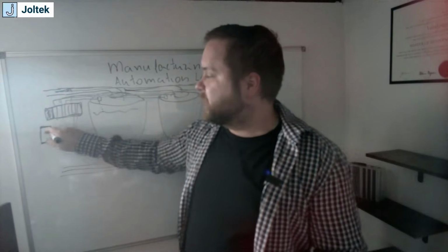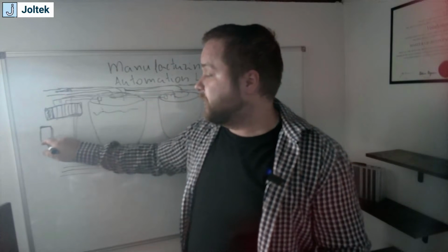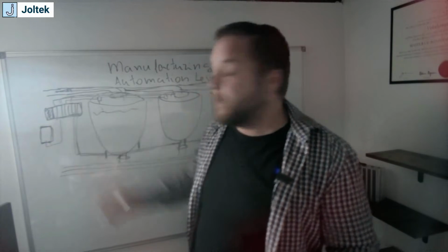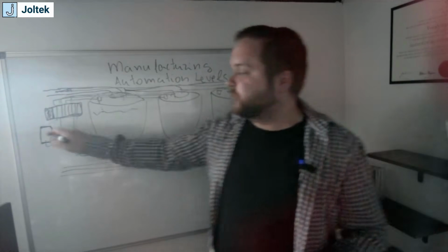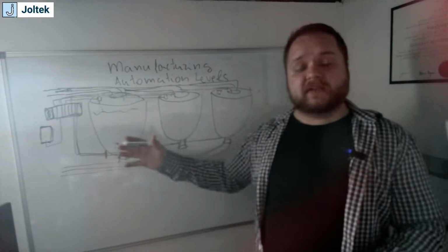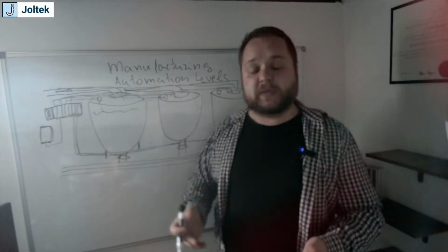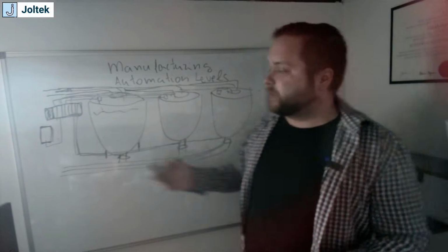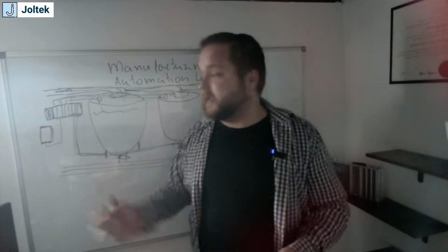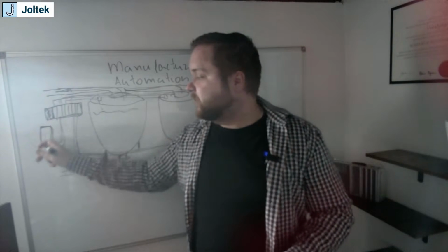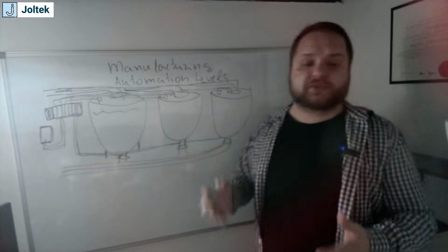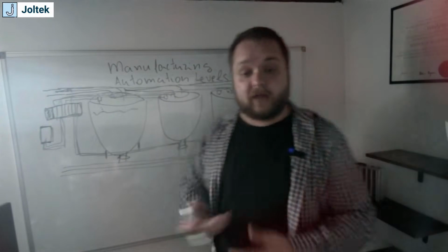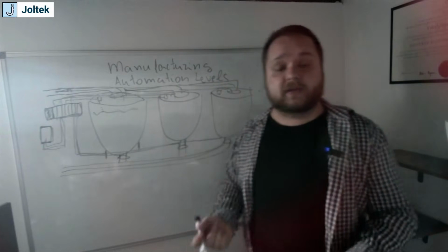The easiest way is going to be to do it via digital inputs, right? So at this point in time, imagine that I don't need to control the speed. I can simply put the parameters in, and so my VFD is going to run at a constant speed. There's other variations as well. So you could set, for example, 3 different speeds, and then you could have 3 digital outputs. And again, we can get into the semantics as to how that's truly connected, but ultimately you have 3 different set points of variation of speed.